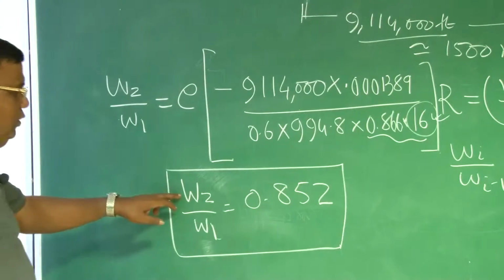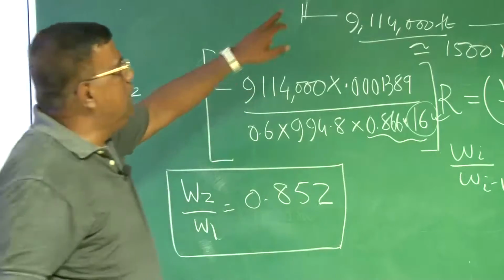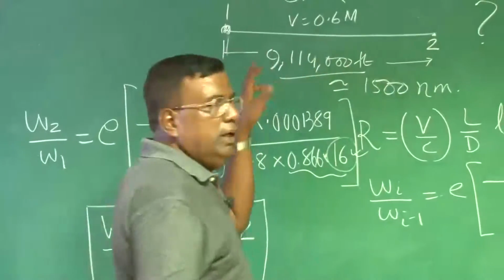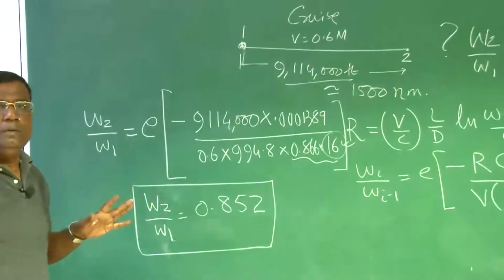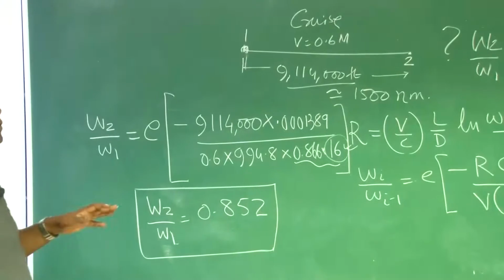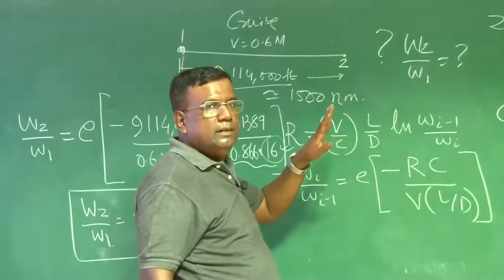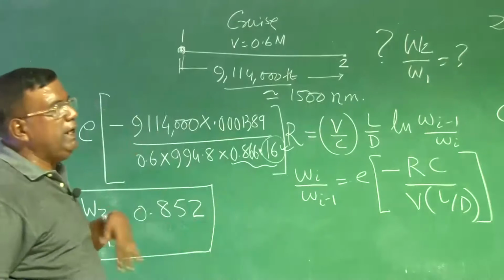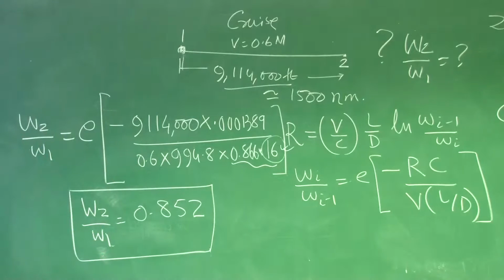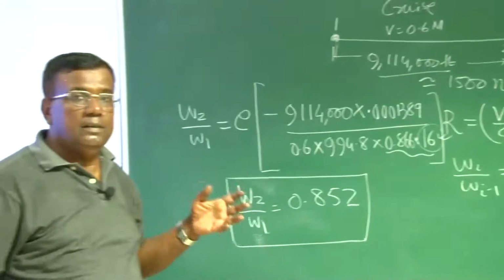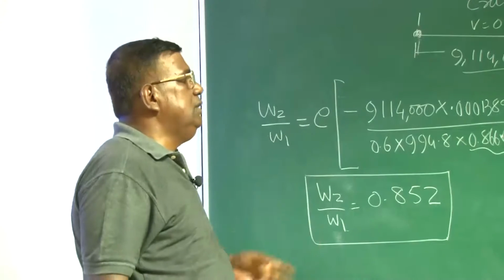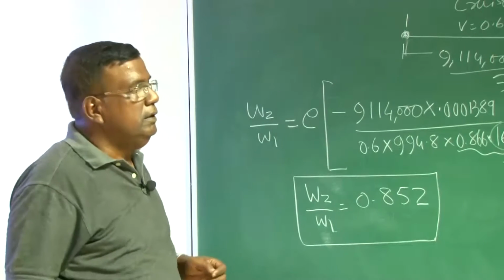So from this ratio, if I know W1, I know how much fuel is consumed during this leg. Right? A similar exercise I can do for loiter also. Only the numbers will change accordingly. In the final example, we will be taking everything together, but it is better that piecewise we are very clear about the units. As I am repeatedly telling, units are very inconsistent, especially C and CT, etc. Thank you very much.